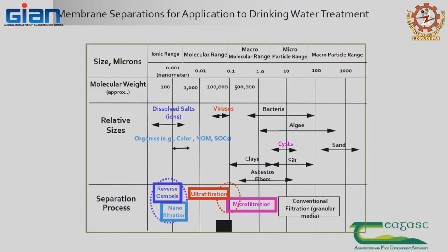Now, this is the last slide for this lecture. One is membrane separation for application to drinking water treatment, process wastewater, all those things. Molecular weight, relative size and separation processes. If it is a large molecular weight, that is again your proteins or so, then you can use ultrafiltration, microfiltration, or simple filtration media. I mean, sand is the best filter.